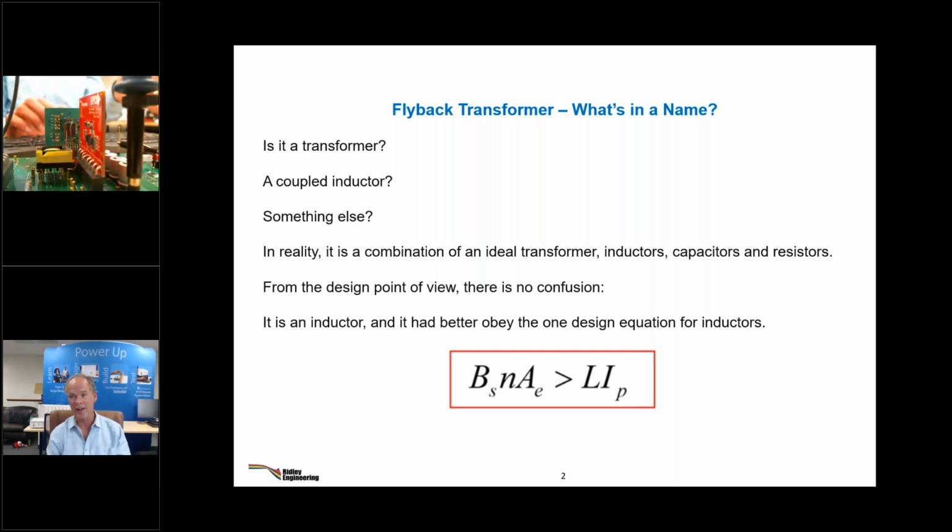All flybacks should be current mode. I mean, all flybacks should be current mode. Otherwise, you can't design the inductor. You turn on the switch. The initial spike of the current sense hits the comparator because it's down at light load, and then it trips it. The next time it trips somewhere slightly different, and then somewhere slightly different again, because you're just on that noise threshold. So it's just jumping around. It's putting out chaotic random noise. Sometimes you hear it, sometimes you don't.